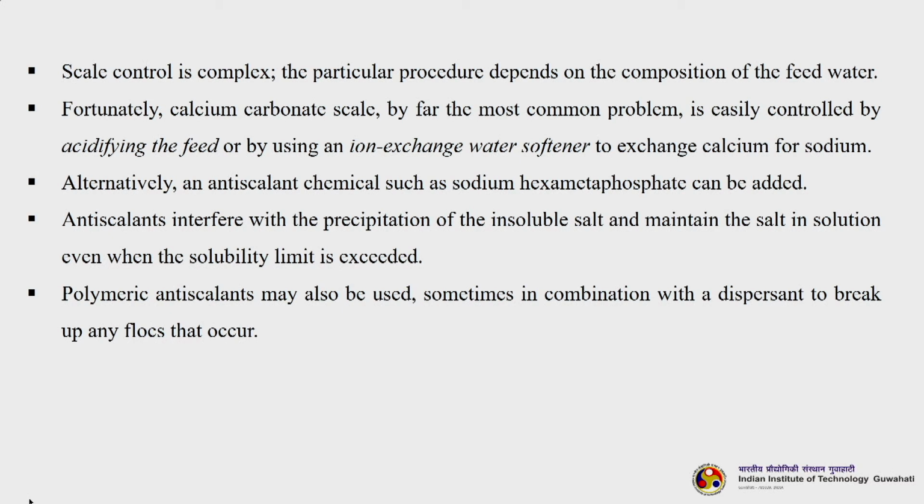Scale control is complex. The particular procedure depends on the composition of the feed water. Since the feed water composition varies, that is why scale control is a complex phenomenon. Fortunately, calcium carbonate scale, by far the most common problem, is easily controlled by acidifying the feed or by using an ion exchange water softener to exchange calcium for sodium.